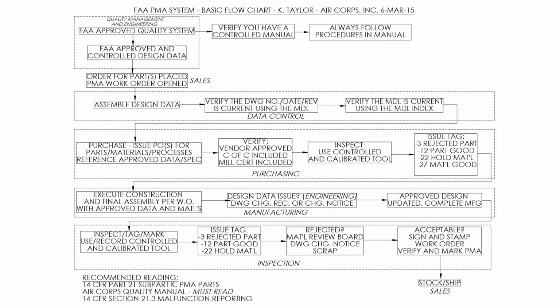Or maybe there was a mistake on a North American drawing. It's possible, you know. But we find out in the middle here that our drawing needs to be updated, or that if we build it to the drawing, it's not actually going to turn out the way it needs to. In that case, again, you can use the drawing change recommendation form. You're going to fill it out: drawing, date, revision, change dimension, 1/8 inch radius to 1/4, please.